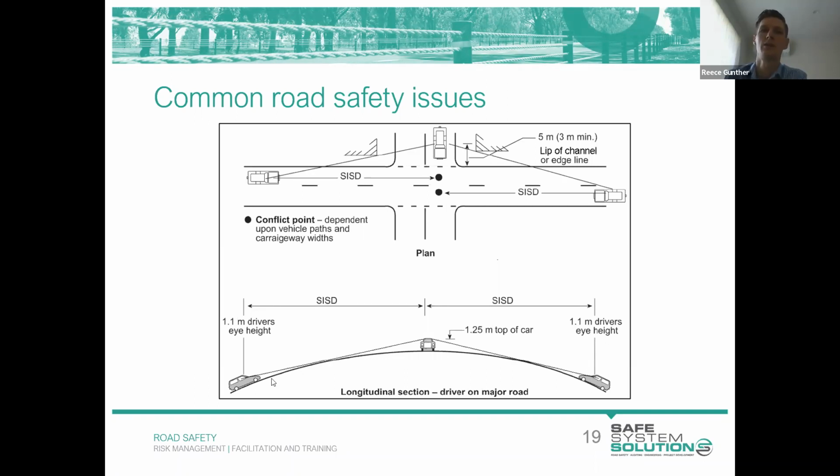One could be earthworks to ensure that sight lines are maintained, as seen here, by having a larger crest curve. The other would be to reduce the posted speed limit. That's a potential as well. So that's how we address it in both circumstances. We do the check vertically as well as horizontally when doing the audit, if possible, through our long sections and so on.